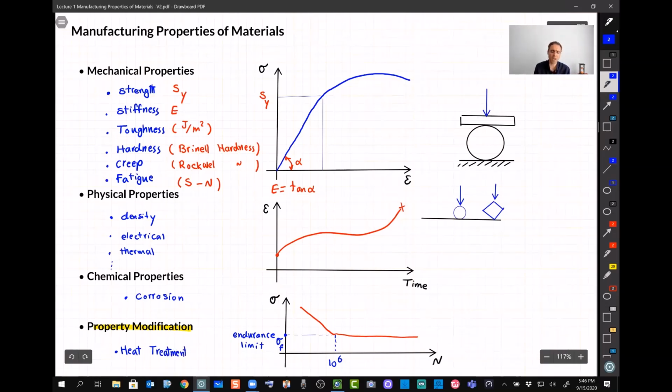And for the heat treatment process, again, there are two main categories: annealing and quenching. In simple words, annealing means heating up a metal to a certain temperature below its melting point. And quenching means putting the hot metal into water, salt water, oil, or maybe other chemicals, and depending on the chemical, we will get different hardness and different surface properties.